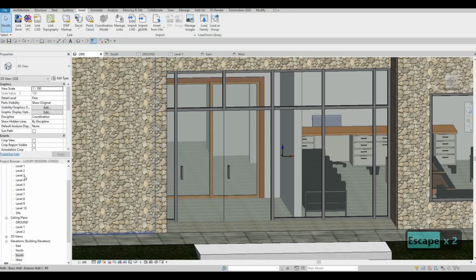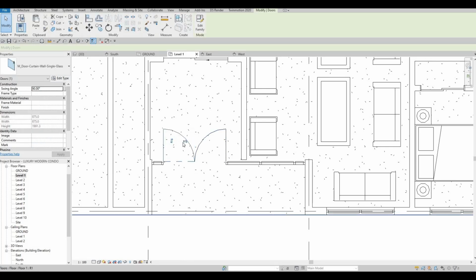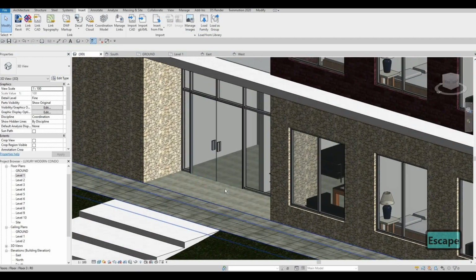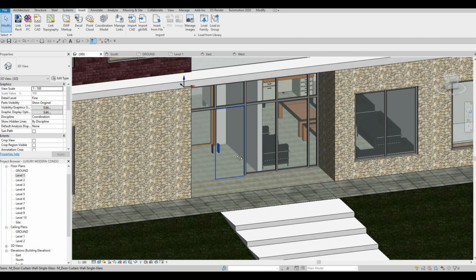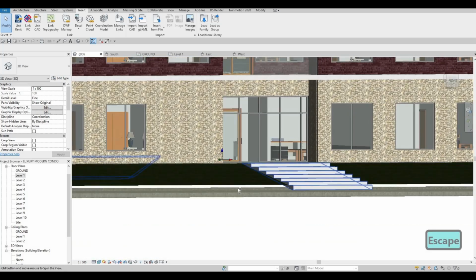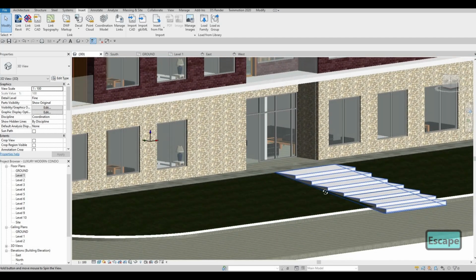And then to flip it, what you need to do is go to level 1 again, and then click this one, and you want it to be going this way, because that's the main door, and if there's an emergency, it needs to go going out. And then we have something like that. So at least it's a more grand entrance.